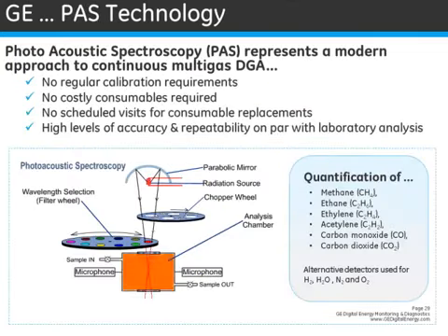Okay, so two slides back, Al mentioned photoacoustic spectroscopy. The multi-gas DGA instruments from GE use a detection system based on the principle of infrared absorption.